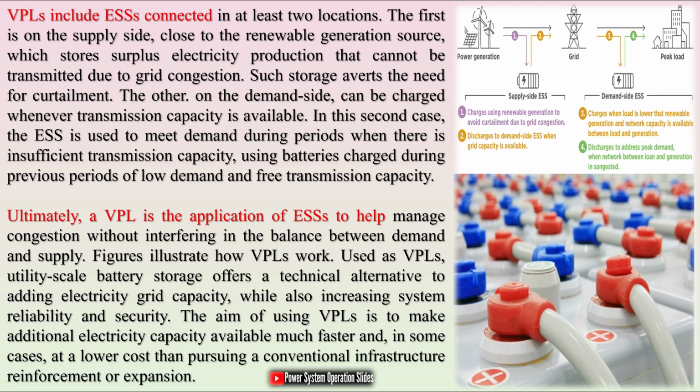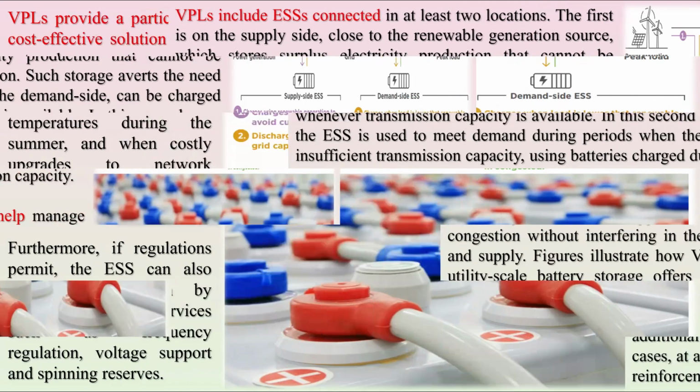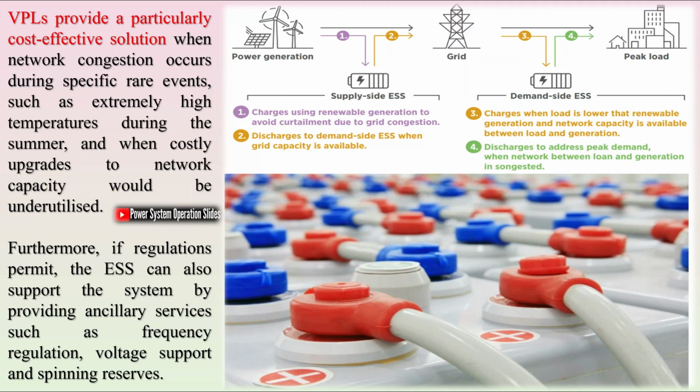Optimization and coordination: an algorithm, an optimal power flow constrained dispatch model. A predictive controller computes a set of coordinated actions, for example charge or discharge a BESS, change FACTS set points, temporarily raise dynamic line ratings, adjust generator outputs, curtail specific DERs.